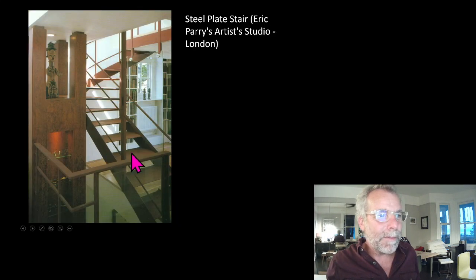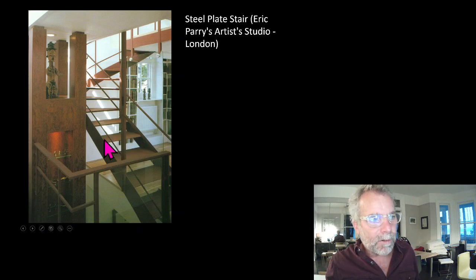So another beautifully minimal stair. I know Shannon was talking about open risers. Open risers will soon be, or maybe perhaps are currently, not permitted in the National Building Code, because they present a tripping hazard, particularly for people with visual impairments. So open risers may very well be acceptable within a dwelling unit, but not in a public stair.